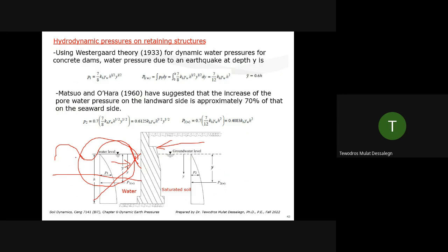And in the other case, this is the sloshing case, you can also have some cases where it separates itself, and in some cases it comes up like this, because it's sloshing back and forth. So there is more pressure now acting on the wall. You may think of it as more resistance, but don't use it for the design. Don't credit it.